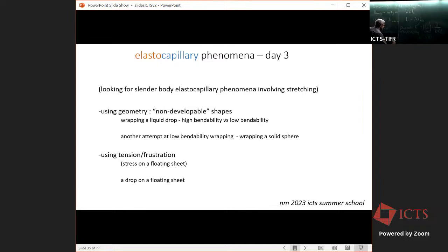You achieve epsilon inverses of 10 to the 6 to 10 to the 8. That's the sort of range you get. And remember this thing is called the von Karman number. You get von Karman numbers, which is just typical size over typical thickness, of the order of 10 to the 8 to 10 to the 12. Okay. So we've not done anything really fancy with materials except made the material much thinner. And I'm going to show you that really gives you access to slightly different behavior.